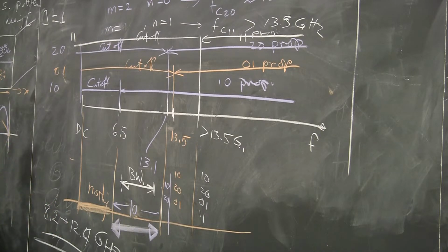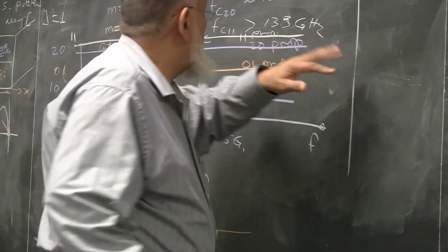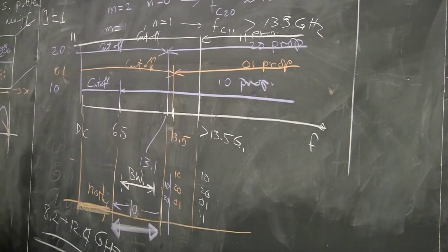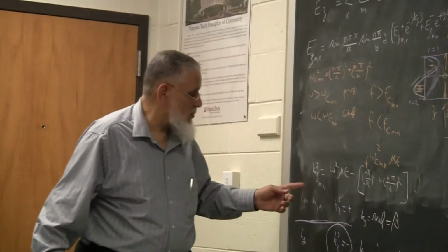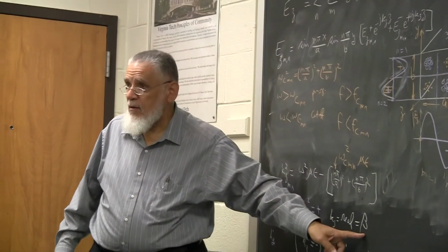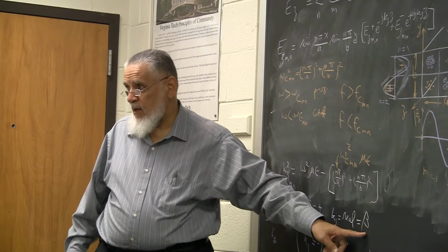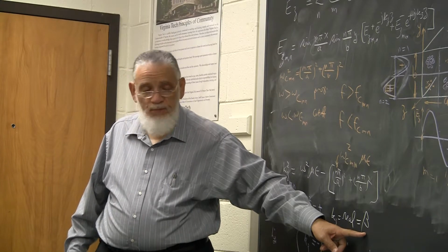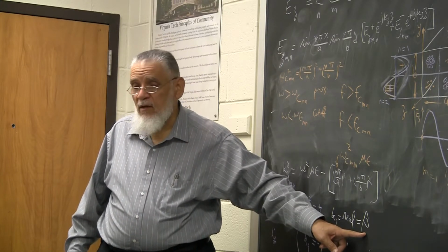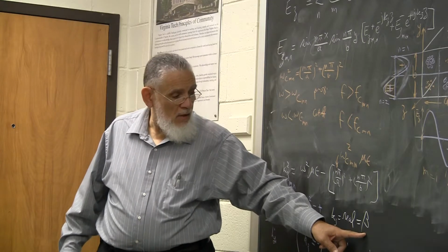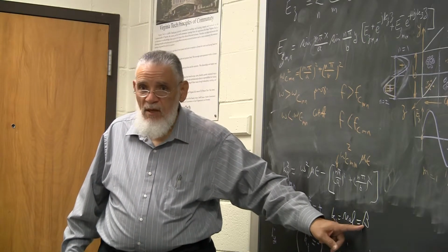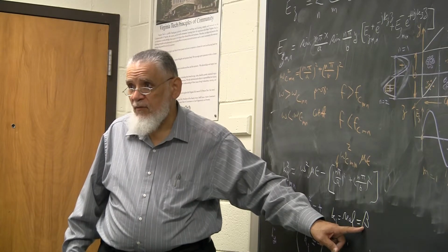When you study the losses in the guide, practical-wise now, getting to practical aspects. So far, we're not seeing any losses. We're seeing a pure, clean cosinusoid with no attenuation. We're seeing our k sub z is simply beta. When you put the practical situation in and work with the losses in the dielectric and losses in the conductor, your k sub z will become complex, and you will have some losses in there.